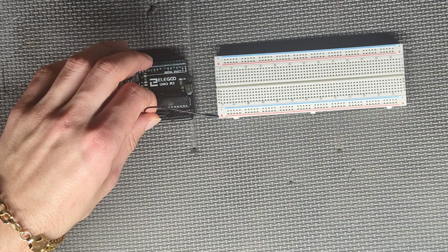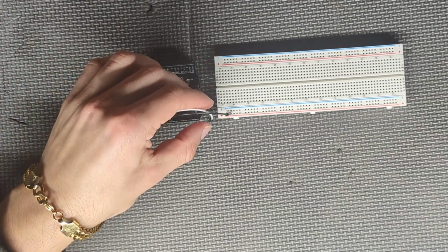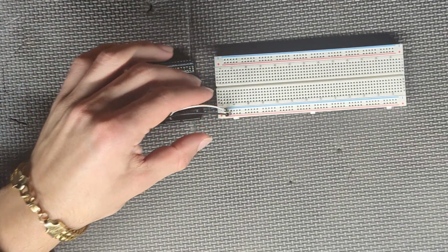Breadboards aren't meant for long-term use as the connections are not permanent and the board can wear out over time. You should instead use a more permanent solution, such as a printed circuit board. First, we'll connect the board to power. We can use a wire from the 5-volt pin and a wire from the ground pin on the Arduino to the positive and negative rails on the breadboard, respectively.